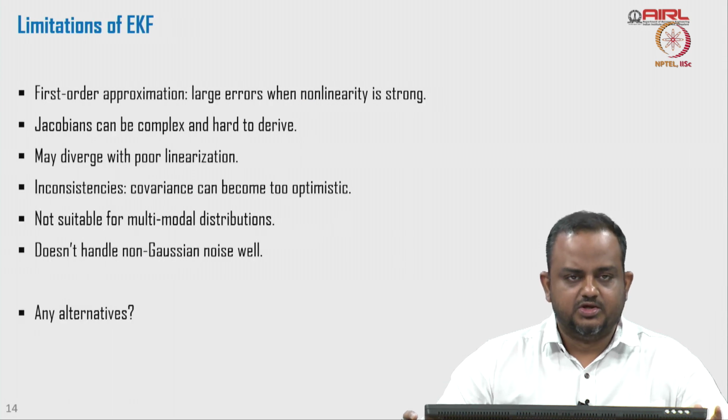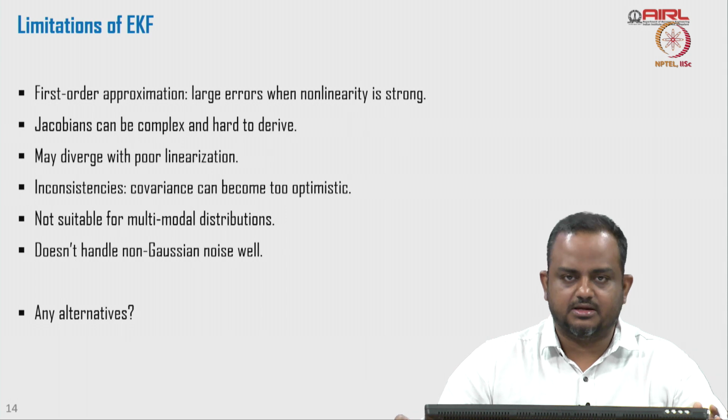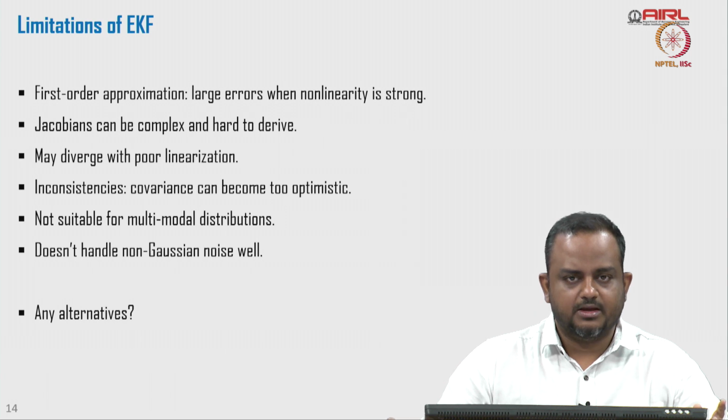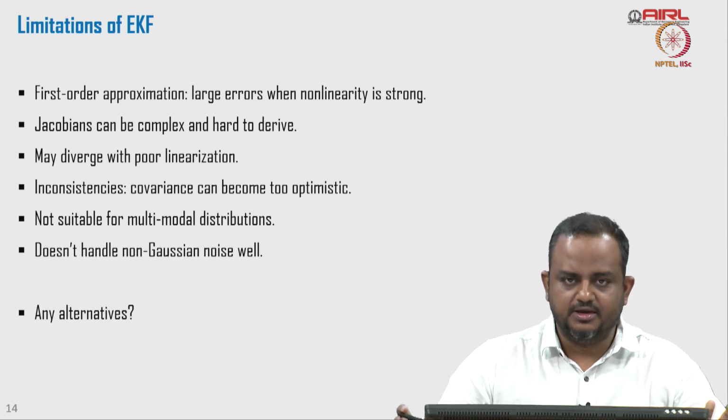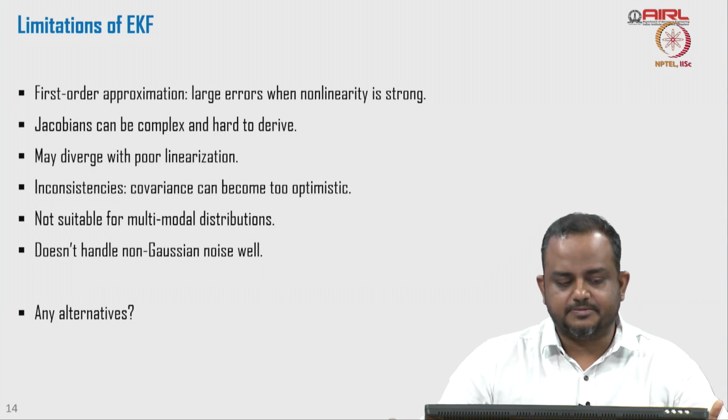Fine. So, what are the limitations of extended Kalman filter? We have seen that Kalman filter fails to accurately estimate the states and parameters when it is a nonlinear model. Why? Because in the example you have seen that sin psi was taken as psi by small angle approximation, but when extended Kalman filter calculates the Jacobian, it has more information within it about the nonlinearity of the system.